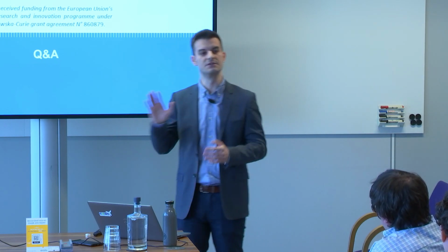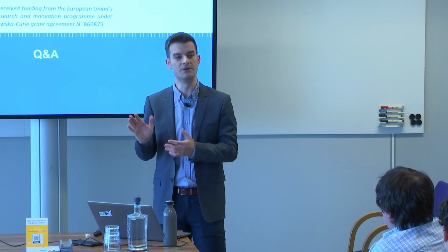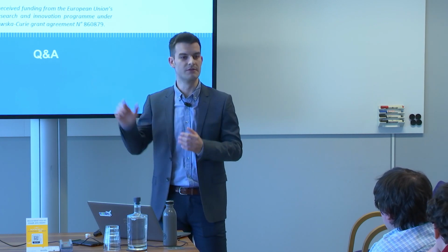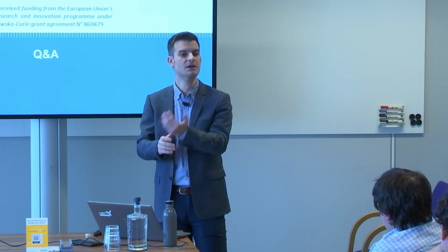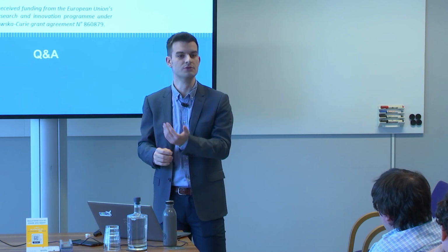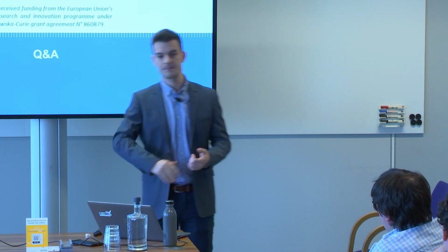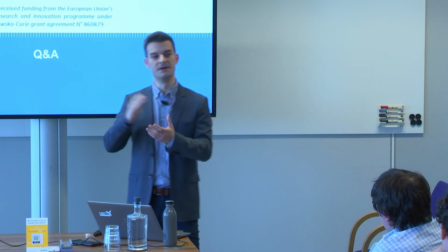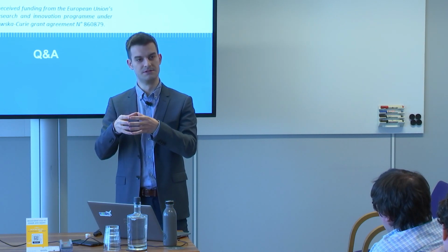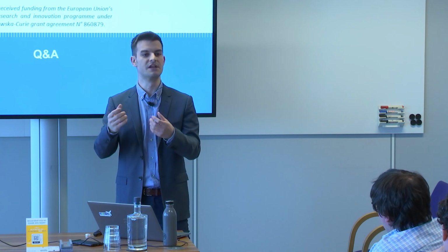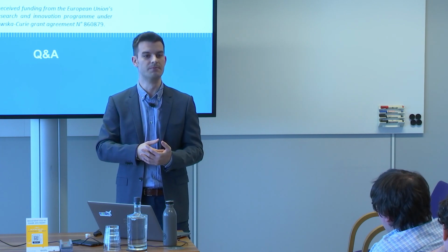Once we start optimizing the design of the tower and the rotor, we can build everything based on fatigue. So we can account for all the load cases that will happen within these 20 years of lifetime. Once we optimize the tower design, we can put the same constraints on the spar platform.